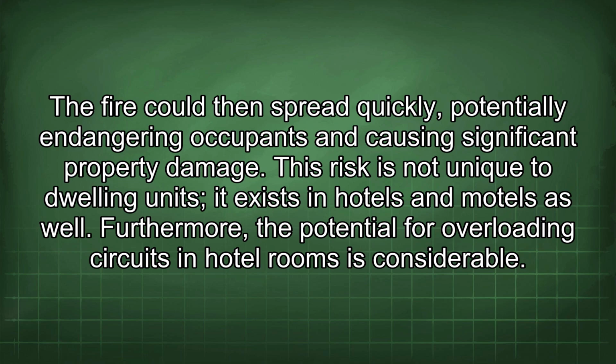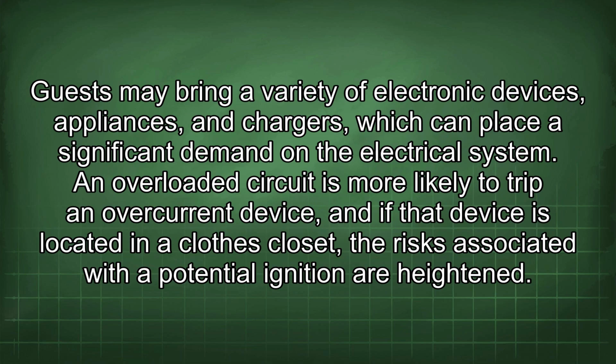Furthermore, the potential for overloading circuits in hotel rooms is considerable. Guests may bring a variety of electronic devices, appliances, and chargers, which can place a significant demand on the electrical system. An overloaded circuit is more likely to trip an overcurrent device, and if that device is located in a closed closet, the risks associated with a potential ignition are heightened.